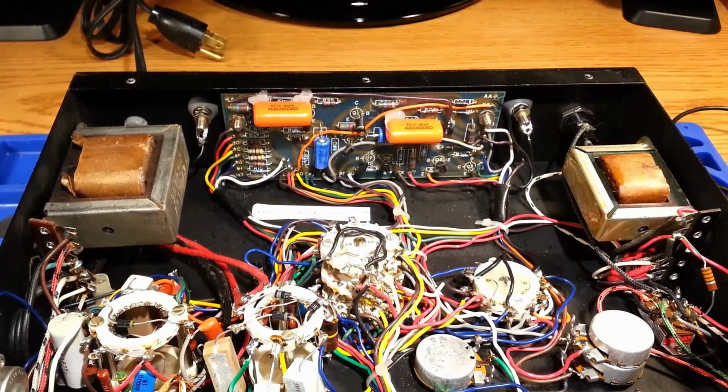So finally got things figured out, got to the point where I can visibly see that fault and do continuity tracing through it to get from the collector connections and the signal transistors to the base drivers for the power transistor driver was what I needed to do. And once I finally arrange the proper positions of the transistors to the schematic, it all made sense again.